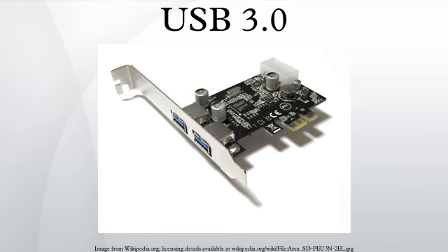On some old Ibex Peak-based motherboards, the built-in USB 3.0 chipsets are connected by default via a 2.5 GT/s PCI Express lane of the PCH, which back then did not provide full PCI Express 2.0 speed, so it did not provide enough bandwidth even for a single USB 3.0 port.